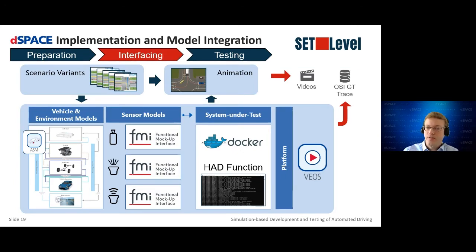This slide shows an overview of the final integration used for the simulation. Thanks to our preparation, the scenario with its different variants is already ready to use. The lower block shows the basis of the simulation, which is dSPACE ASM, which stands for Automotive Simulation Models. ASM provides the environment model and controls the scenario execution. External vehicle and sensor models, camera, LiDAR, and radar, are all integrated into the ASM model.